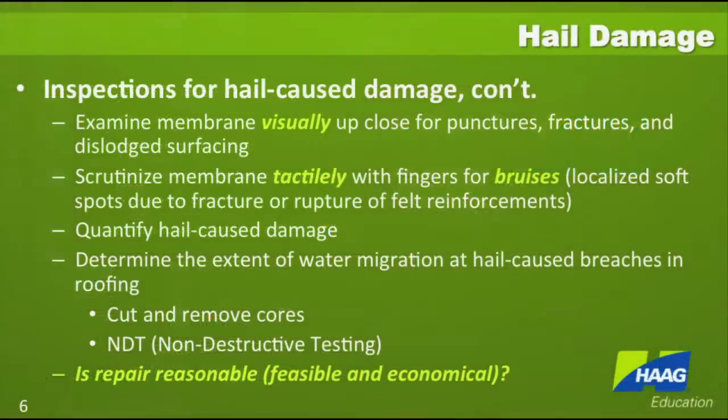If you've identified actual areas of hail damage in your test area, quantify those, and in addition to that, you're going to have to quantify the damage to the more susceptible areas, such as parts of curbs and parapets that may be damaged.